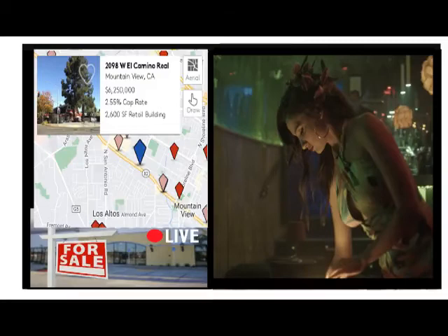For example, a 36,000 BTU, 3-ton, air conditioner that needs 6,000 watts to run has an EER of 6.0. A unit of the same capacity that needs 5,000 watts to run has an EER of 7.2. A higher EER means that less energy is consumed and the unit is more efficient.